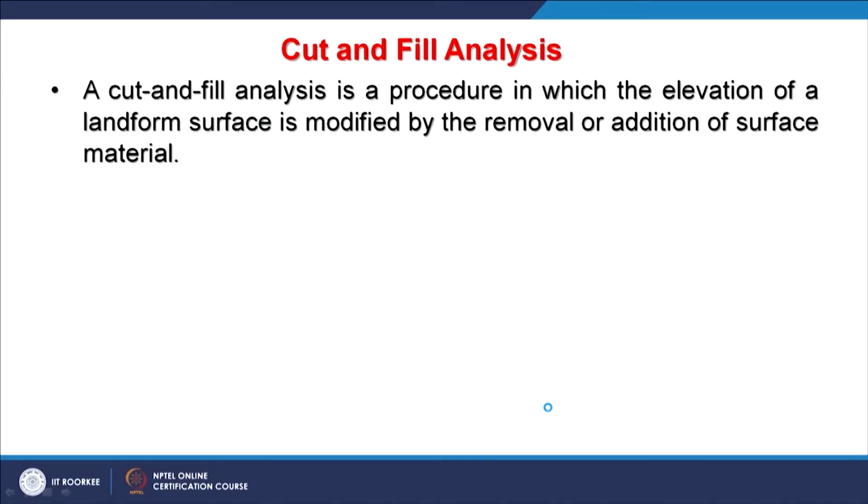Now, part of this surface volume analysis is cut and fill analysis, which I mentioned earlier. This is a procedure in which the elevation of a landform surface is modified by removal or addition of the surface material. So, where this material has to be cut from and where it will be filled can be decided based on this cut and fill analysis. And in this analysis, the areas and volumes of change are summarized.